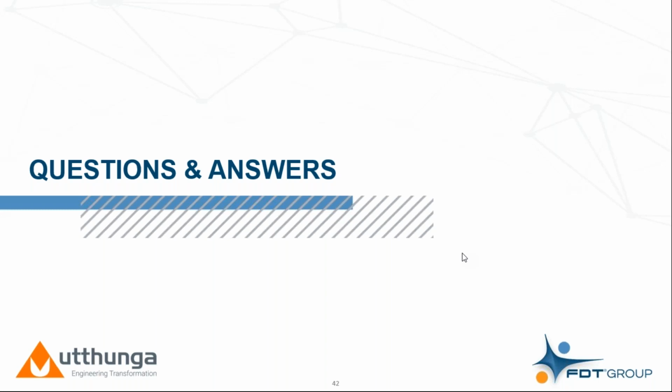Yeah, sure. Is there any COM DTM available based on OPC UA? Glenn, it would be good if you answer this. I missed the beginning of that question, Smitha. Is there a COM DTM available based on OPC UA? No, because the OPC UA server is built into our server. We didn't have to issue a specific COM DTM, as it were. We offer a native OPC UA interface. Now we are watching very carefully, obviously, what the OPC Foundation is doing with their new field protocol. And I think once that gets some more specifics built around it in terms of how that's going to work, then you would probably see a communications DTM for FLC.